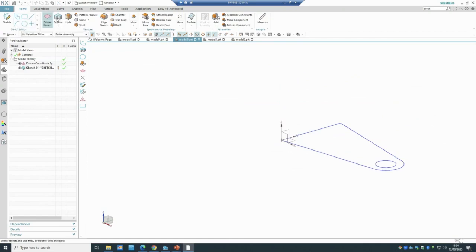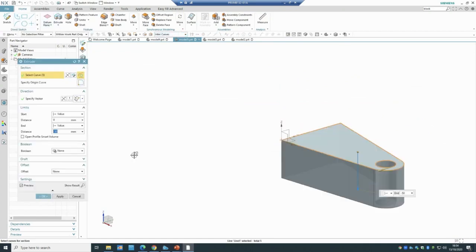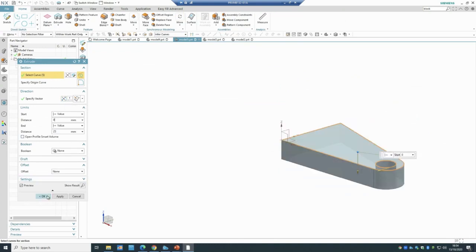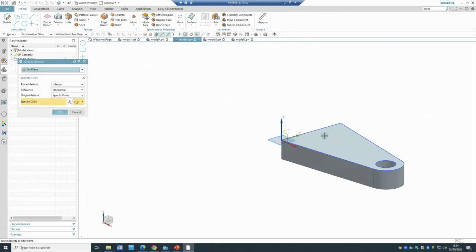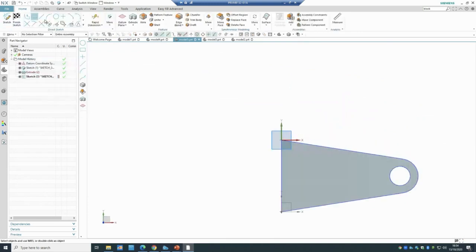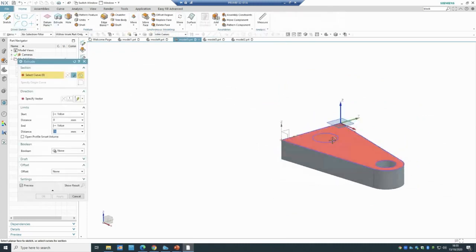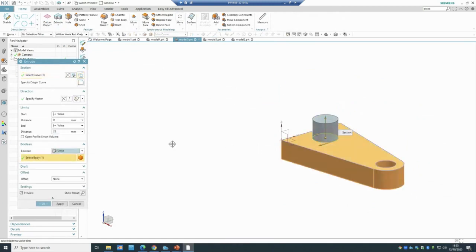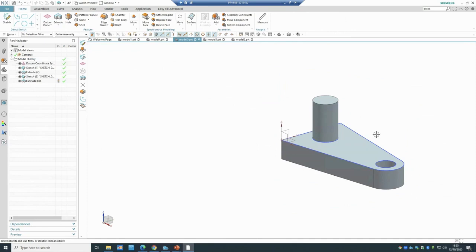And I'm going to do an extrude. Let's extrude it for the other direction, 25. Okay, now I'm going to do another sketch. I'm going to use this plane this time. Click OK. Let me create, yeah, let's create something like that. Okay, I've finished the sketch. I'll extrude this one. And if you remember, this one I will change to unite, so they become one body, and I will do an extrude of 50. Okay, great.